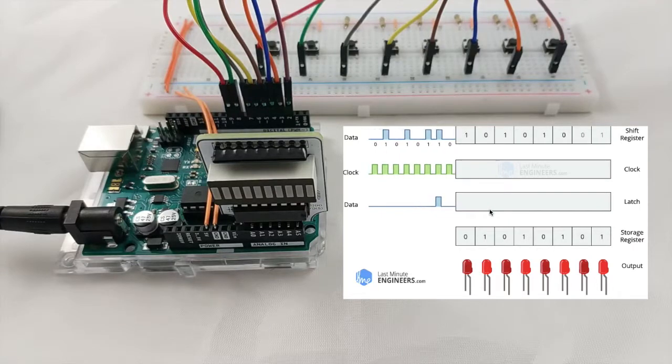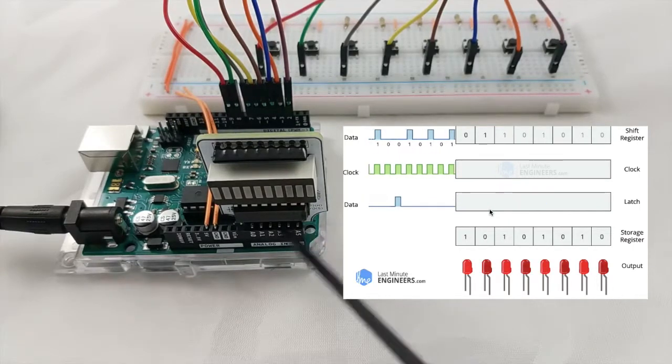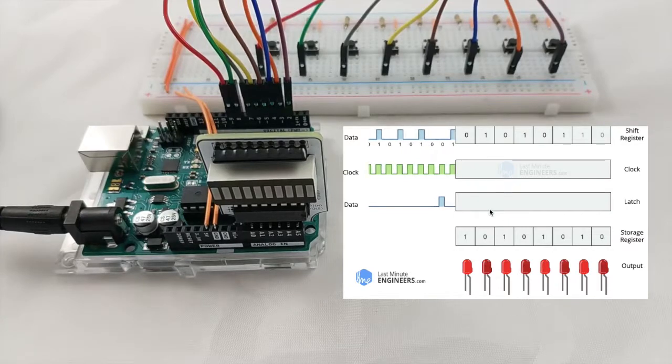A steady clock pulse is fed to the shift register's clock pin and provides the spacing of the bits from its frequency that the data pin must recognize. When the latch pin is pulled low, the byte fed into the data pin is read but not displayed on the bar graph. When the data transfer is complete, the latch pin is pulled high and the data is presented via 8 individual bits on the IC's output pins, illuminating some LEDs.